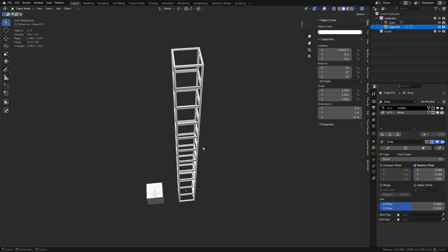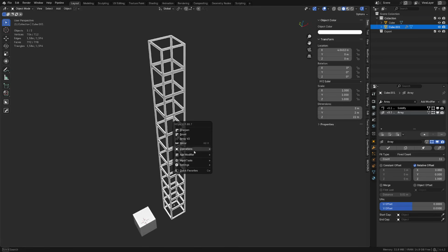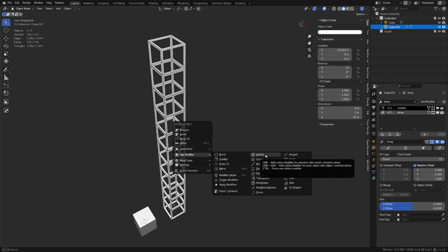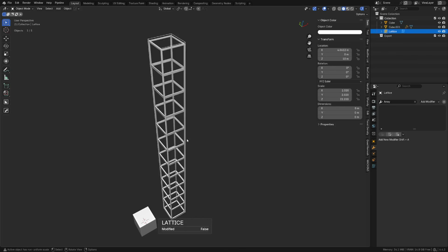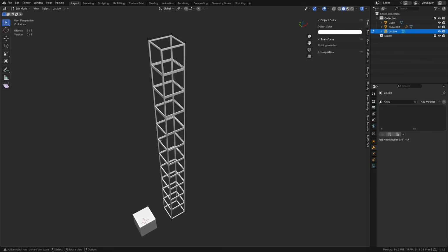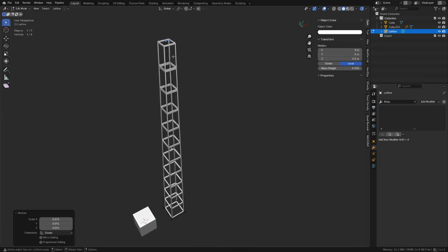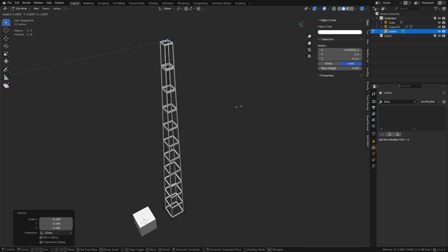So what can we do here to make this happen? Well, there's a couple ideas. First, maybe we try something like a lattice, right? We'll use Hard Ops in this case to just create the lattice. It's going to create the lattice object. Doing that without an add-on is a lot more painful, but use Hard Ops or the Modifier List add-on. It's much easier. But when you create the lattice object, you just scale these in. You can even negative scale them if you wanted to.